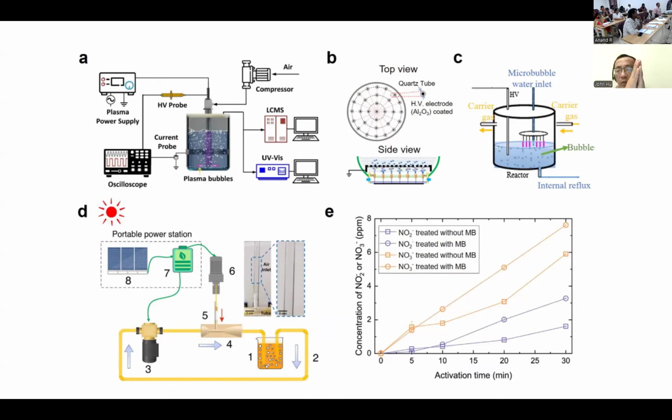But if you have a gas phase reaction, which means DBD, you probably can scale up and multiply your reactor. Once you get aqueous phase, it limits your reaction because your reaction is dependent on the surface area. It's a limited surface area you can use, but you deal with a big vessel of liquid phase. In a bubbler reactor, or in the reaction at the interface between the liquid and the electrode, there's a lot of debate going on about how you scale up this reactor.